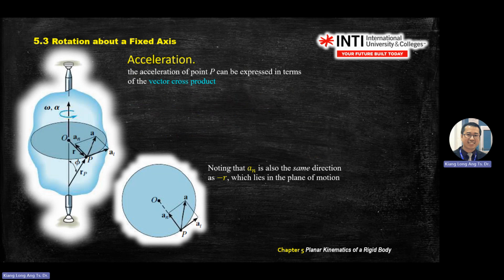Okay. Now this one is a little bit of derivation on the equation. a equals dv dt. So v equals omega r. Or in vector form, in three-dimensional analysis, you have no choice, you have to use cross products. So v equals omega cross r. We always take omega cross r. Look at the axis of omega, then use your right hand, pull from the omega axis to r.